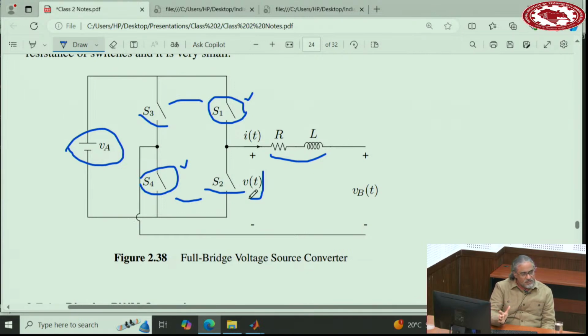And you can hardly see any people using single phase inverters that decide to go with bipolar. They all go with half. If there is any disadvantage, which I'm not sure, the advantage is significant. We are in the area of engineering, I agree with you that there should be some disadvantage, but let's figure that out later. As far as I know, the advantages significantly outweigh the disadvantages. So almost every application that uses a full bridge converter or full bridge inverter operates it at unipolar. Okay.